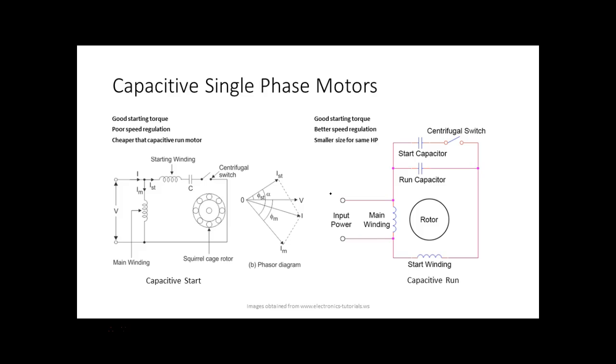But you can order them online, but you need to look at the can, and it'll have so many microfarads at so many volts, and that's what you need to look at in order. If you put the wrong capacitor in there, it might not start, or it might burn up your coil because you have too much ratio. So the size capacitor depends on the induction of this coil right here, and that depends on the manufacturer. So on the side of the capacitor, it has so many microfarads on it.